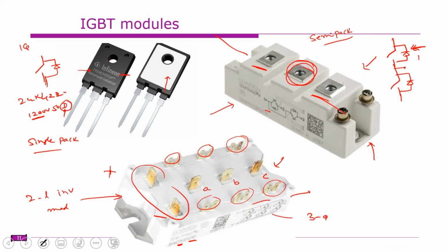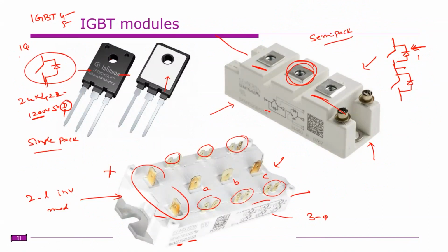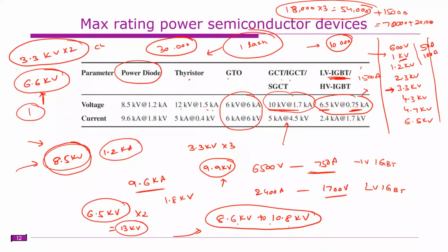We have generations, IGBT 4, 5, 6, something like that, meaning first generation, fourth generation, fifth generation IGBTs. We have different manufacturing or fabrication processes, such as trench stop, field stop, and others. That means if the device has failed, in most cases it comes with an anti-parallel diode, unless some applications require only the IGBT itself, in which case we purchase that.